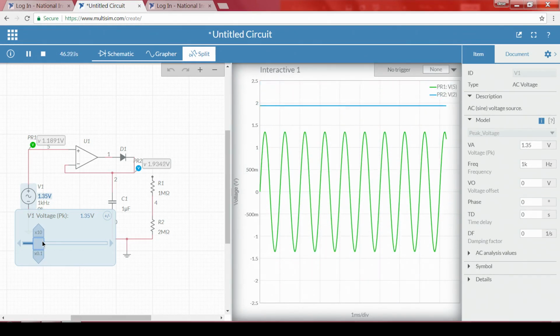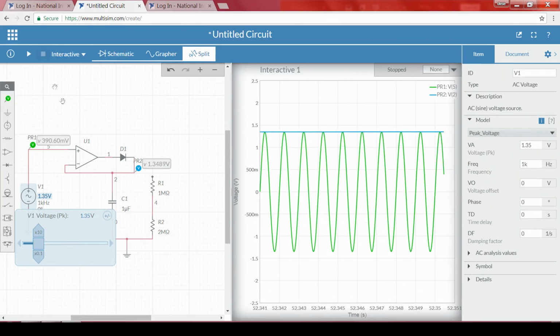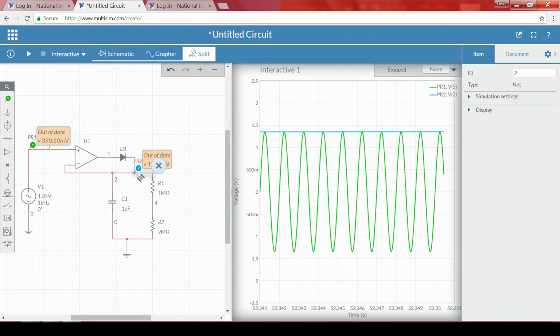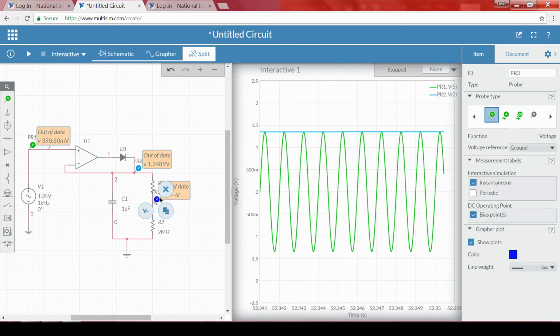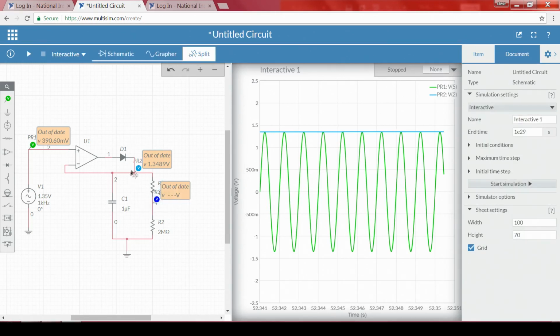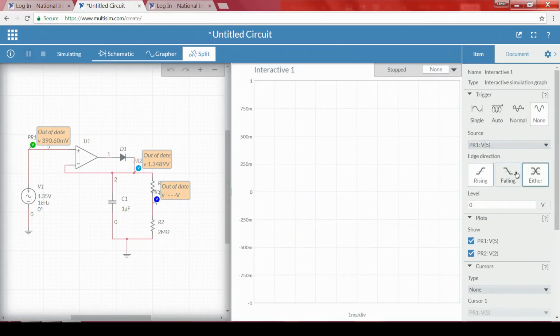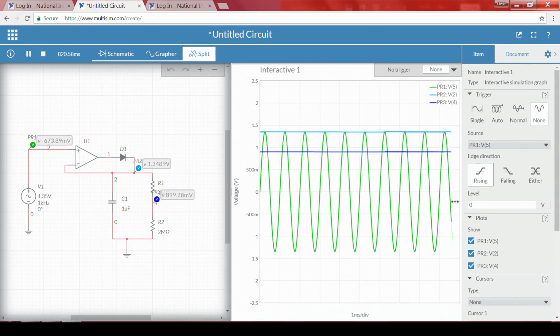Now, what is our other purpose? We have to see whether it is providing the threshold of our requirement or not. In order to understand that, what do we do? We will connect this R1 resistor and take another output voltage at this point. This particular terminal I am not interested in. Let me run, and even if it is there, no problem for us.